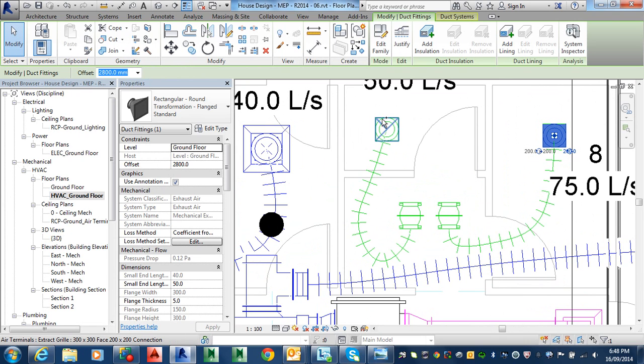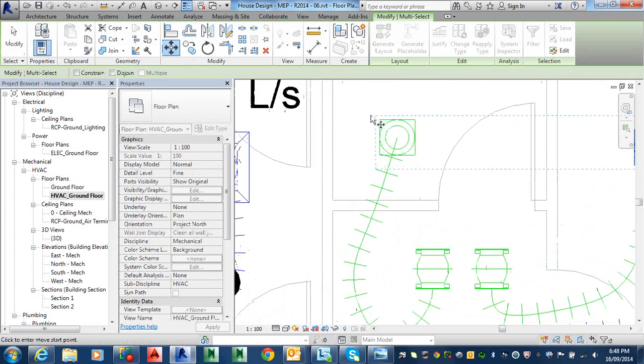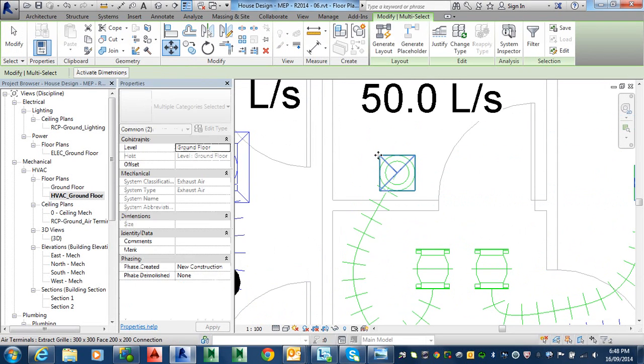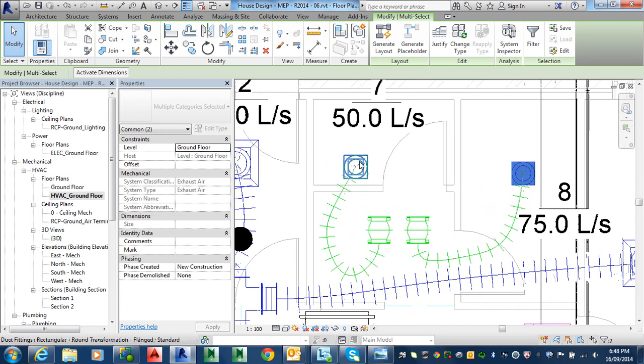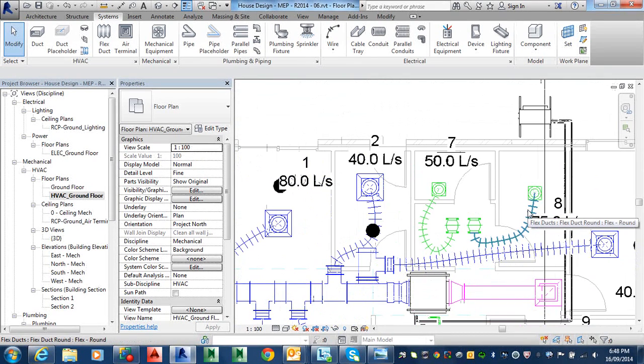If it's not, you've connected your ductwork to the wrong side of the fan. So it should be green. If it's not, just disconnect a piece of duct. And I'll come around, give me a check.